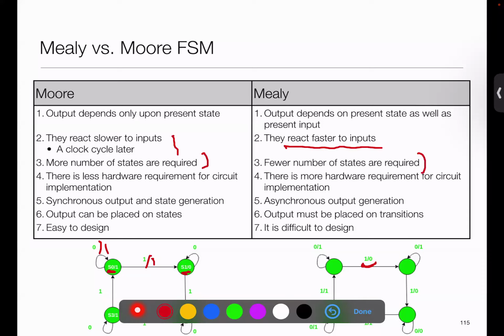On the other hand, Moore generally tends to have a simpler combinational circuit, whereas Mealy tends to have a more complicated combinational circuit. Part of it is simply because the output depends upon both input and state. Very importantly, not only does the state change at the clock tick, but in the case of Moore, since the output depends on the state and the state is changing on the clock tick, the output also changes only at the clock ticks, right?